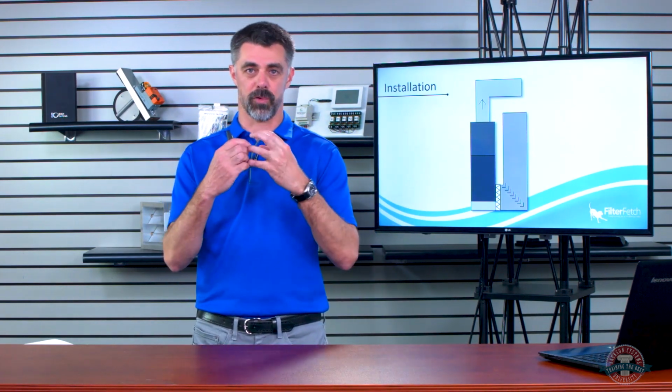And then I got another question from Robert. He wants to know, how much exposure would it take for that sort of breakdown to be visually evident on a filter? I have come across one where somebody installed a UV light incorrectly in line of sight with the air filter, and I don't remember the time frame that it was in there, but it had holes large enough. It was less than a year, but it had holes in the filter large enough that I could stick my fingers through it. So it was significant damage, and that's where it just got brittle and came apart.